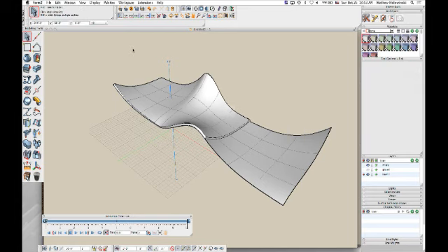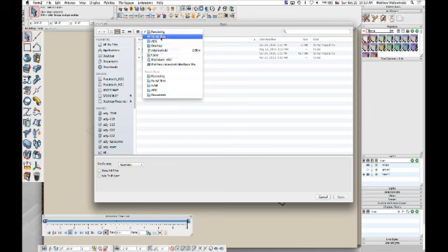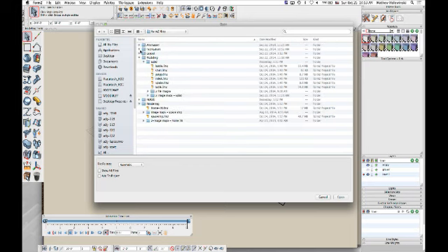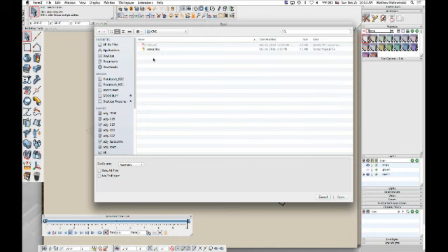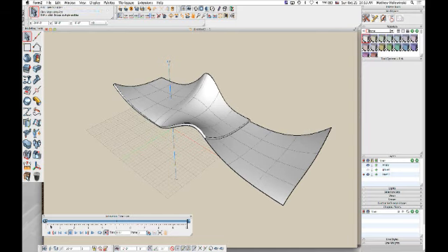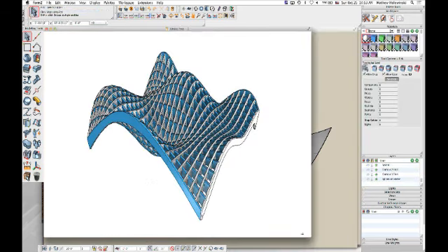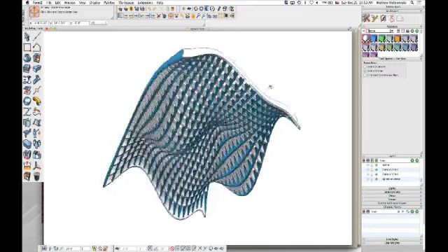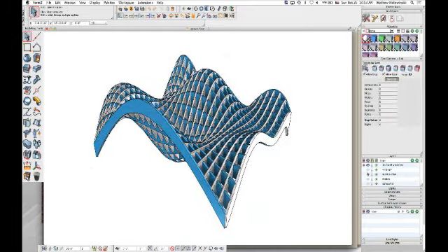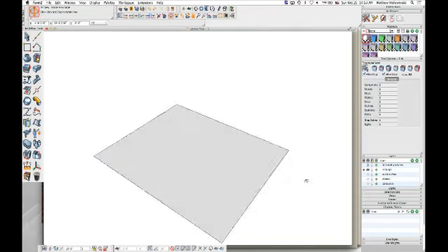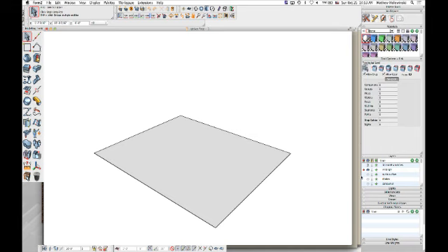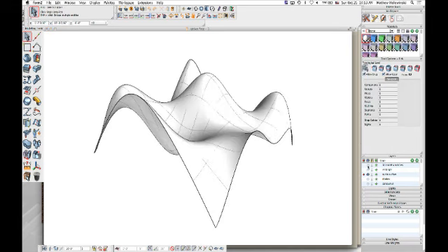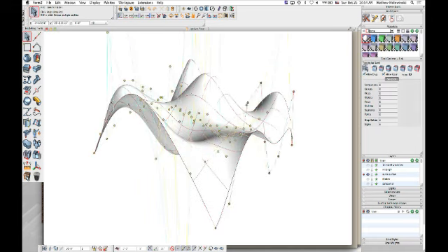Let's open up that. All right, first thing I'll do is just take a minute or two and fast forward through the workflow of how you would create something like that. And here's the actual final conceptual model that we have there. And what we did is start off with a 2D rectangle. All right, and we take that rectangle and we convert it into a NURBS object. We just did that previously. Convert to NURBS. We can take those controls and move those around, right? So we can articulate that and move those controls.